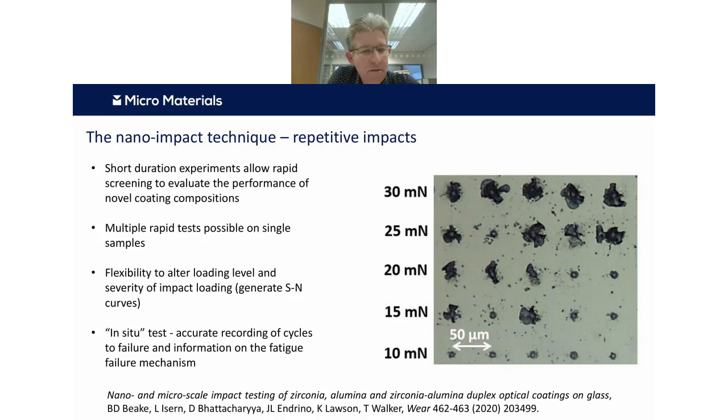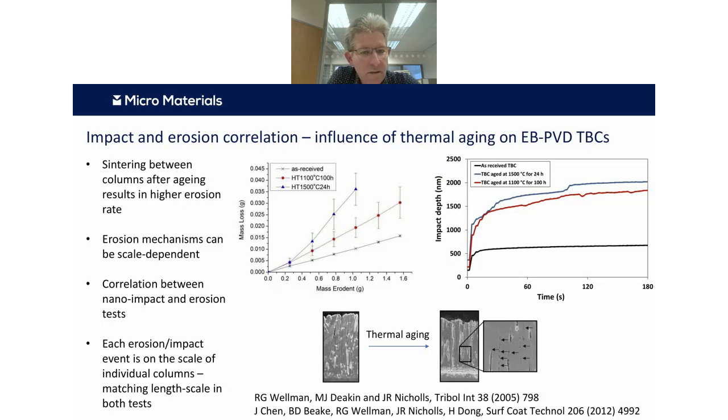Each of these tests, as well as the microscopy that you can see on the right, also has all of the depth versus time data and the number of impacts to failure data associated with it. So you can build up these very accurate pictures of time to failure. And as I said, it correlates very nicely, typically, with erosion testing.